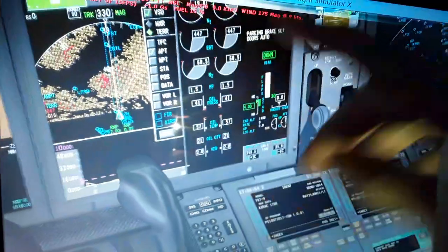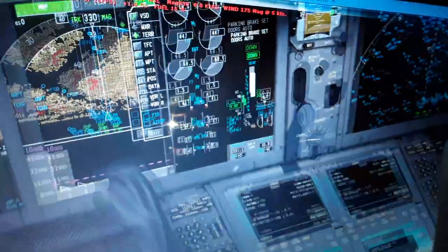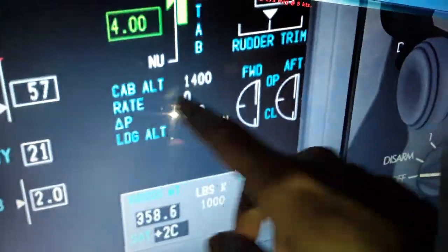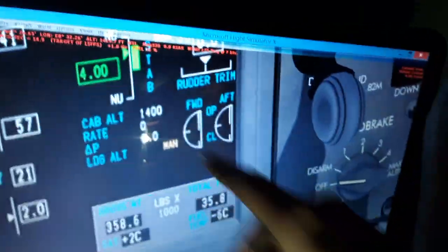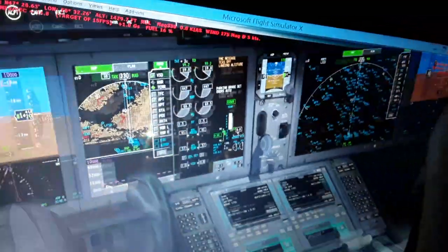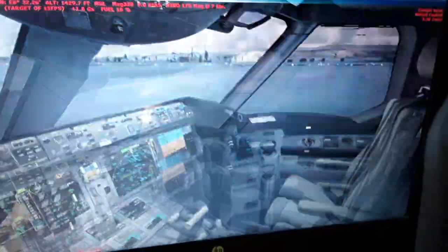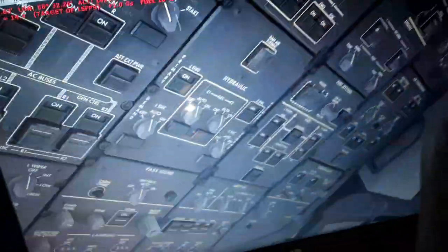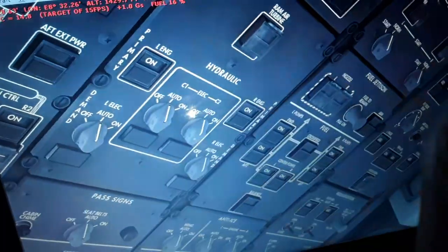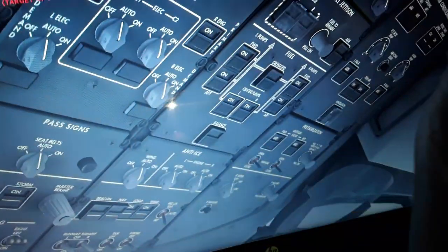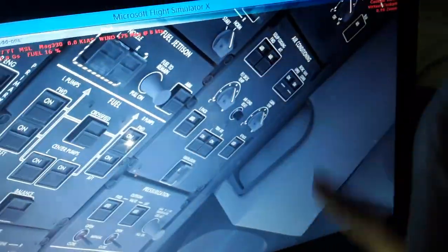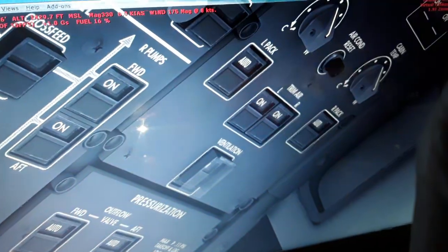So you will see also the engine indications. We take bleed air pressure from the engines, as most aircraft do, to pressurize the cabin of the aircraft when flying. Also the hydraulic fluid tanks, other systems, wing and engine anti-ice over here. So hydraulic fluid tanks need pressurization from the engines. Anti-ice needs bleed air, and so do cabin pressurization, air conditioning, ventilation and oxygen in flight.